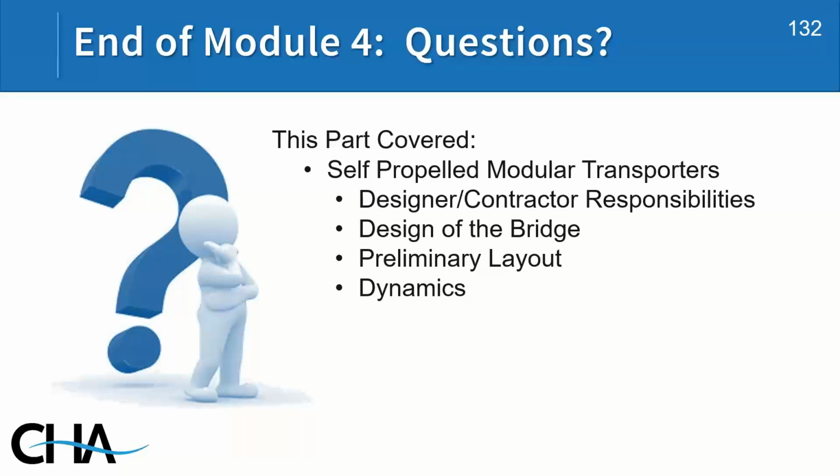We have worked with numerous heavy lift contractors, and typically they were using numbers in the order of 5 to 10% for horizontal dynamic force to design the false work. There really was no vertical dynamic effects that were being used. So the research was very useful. And what we're finding out, the provisions in the guide spec and in the NCHRP guideline will give us numbers in the order of about 7% of the dead load of the bridge is your typical horizontal dynamic force.